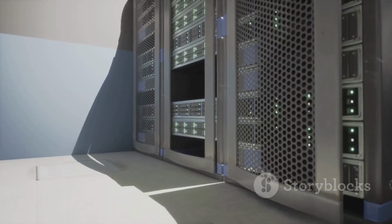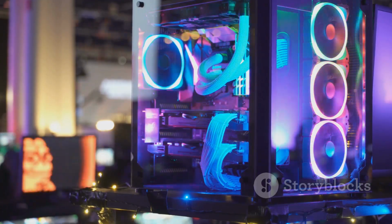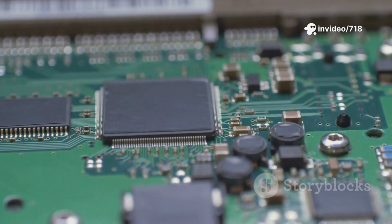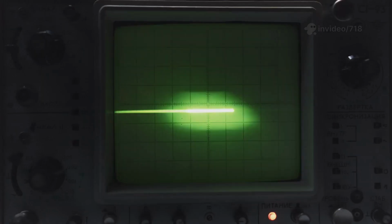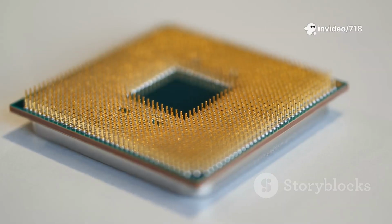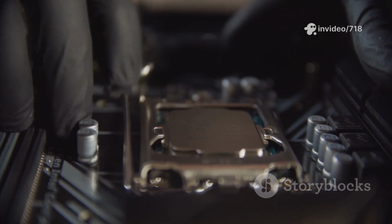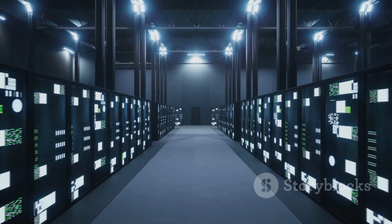A new approach was needed to close this growing performance gap and allow the system to operate more efficiently. The solution was to make the memory synchronous with the rest of the computer system. This led to the development of synchronous DRAM, or SDRAM. The big idea behind SDRAM was to introduce a clock signal that would synchronize all the DRAM's operations with the computer system bus. Now, instead of the CPU just waiting, it knew exactly when the data would be ready, based on a set number of clock cycles. This allowed for a much more organized and efficient flow of data.